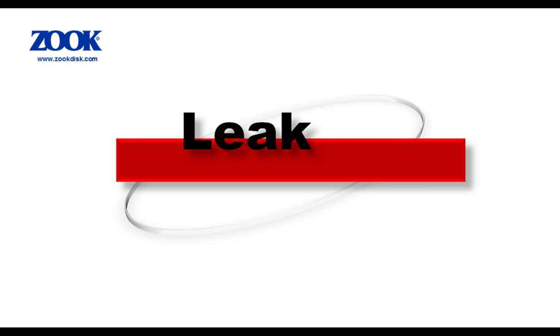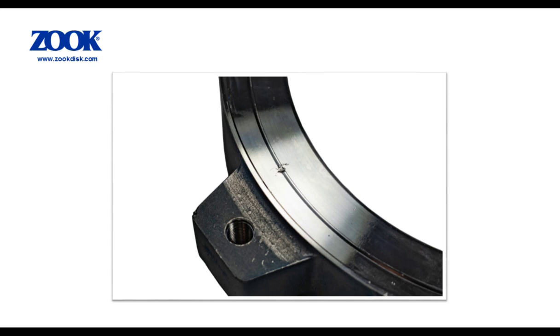There are various methods used to seal rupture disc within the assembly. This varies from manufacturer to manufacturer, but it can include O-rings, pinch points, welds, metal bites, etc. Care should always be taken when handling holder sealing surfaces, and they should be inspected every time a disc is changed. Any damage to a sealing surface can cause a leak. In this picture, you can see that the raised sealing bite section of a holder has been damaged, which could create a leak path in the assembly. Not all holders or disc assemblies are suitable for every situation. If you're confident that your discs and holder sealing surfaces are not damaged and that you're following proper installation procedures, then you should contact your disc manufacturer for help.